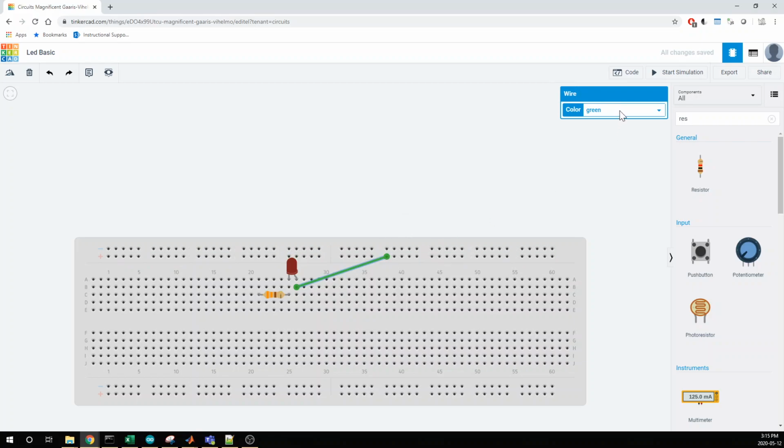And the wire color comes up as well. So the color doesn't matter in terms of electrical conductivity. It really makes no difference. But where the wire color matters is for you to organize your circuit. As your circuits get larger, you probably want to follow a color code. A standard color code says that power or high voltage is red, and reference voltages or low voltage is ground, which is black. And then anywhere in between, if you're doing connections in between, you want to stick to a consistent coloring. Sometimes you use white, sometimes yellow, whatever happens to work for you. But typically what you want to do is make sure that you are following some kind of color convention. So my color convention is that high voltage power lines are red.